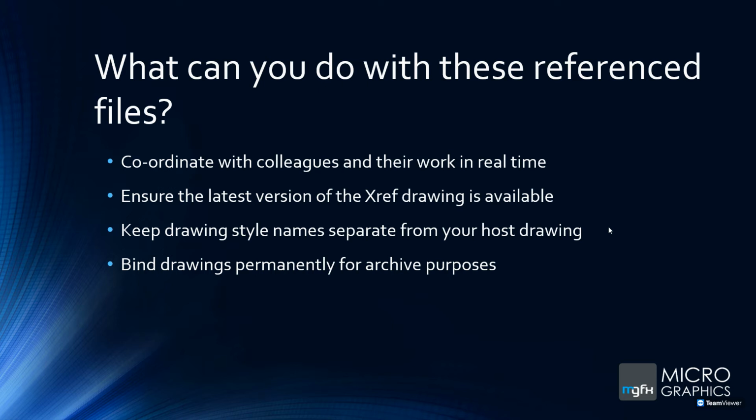And then a nice thing about this: because an Xref is referencing other drawings all over the place, on the server, on your computer, on someone else's computer, it allows you to bind those drawings at the end. This is great for archive purposes, because once you're done with a project, right, now I need everything that's involved with this project to be in one zipped file or one folder.